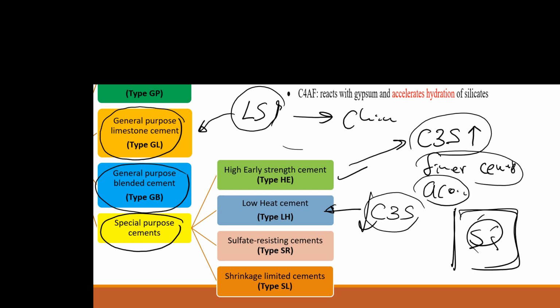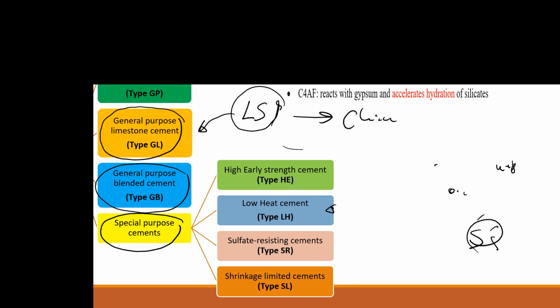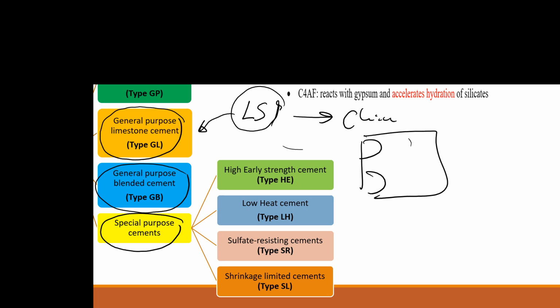So what do you know about air entrainment? You have this again in your lecture notes. What do we mean by air entrainment? When we mix concrete, just like when you are mixing a cake, you can see air bubbles trapped in the mix, isn't it? That air we call accidental air. It stays in lumps in different places of the concrete. This is undesirable, as it affects the strength. So we need to get rid of this accidental air. We vibrate and compact when we pour in concrete.